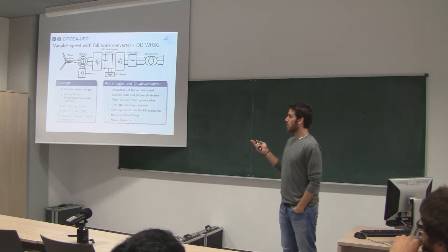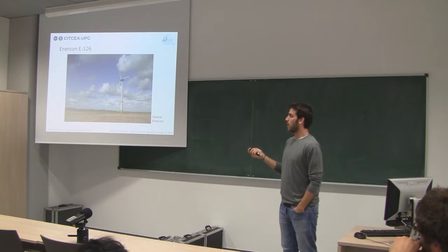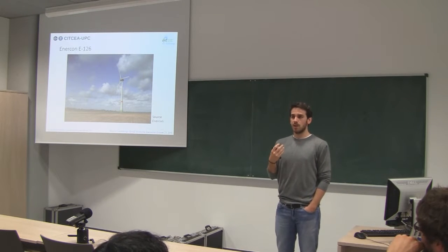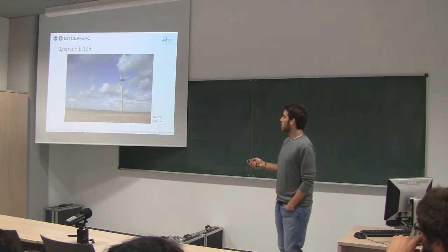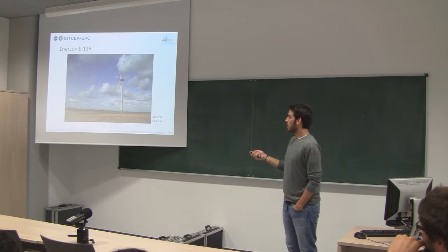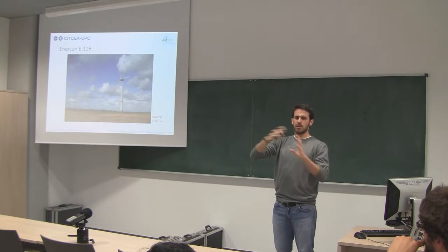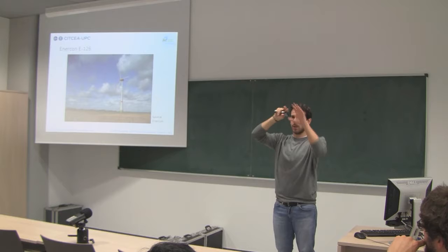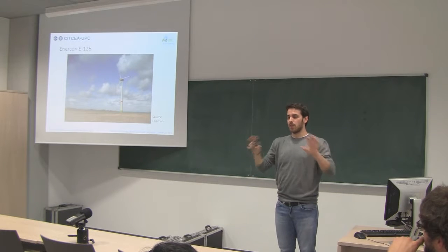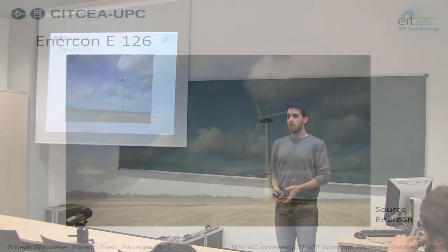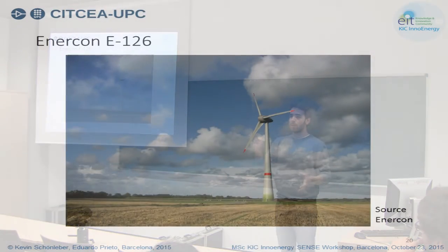So who proposed this concept? This has been basically proposed by Enercon. This is one of the latest machines, but they have been installing this system for a while. So here you can see that in the nacelle, it is a bit wider, so they have to include the multipolar generator in the nacelle, so they have to fit it here.